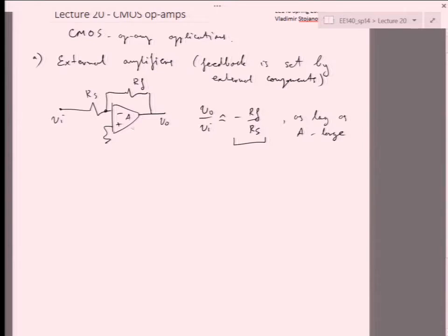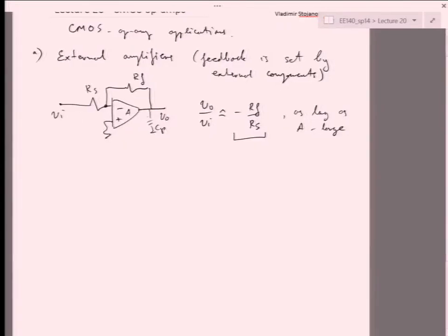The challenge in building this type of op-amp is that it has to handle a whole bunch of parasitic conditions. You take this op-amp off the shelf, put it on your board, put all sorts of things around it, and there are a lot of components that you introduce unintentionally. So the op-amp has to be able to drive all these external parasitic capacitances. Therefore, the stability of the op-amp matters, since, as we talked about last time, feedback does affect stability.